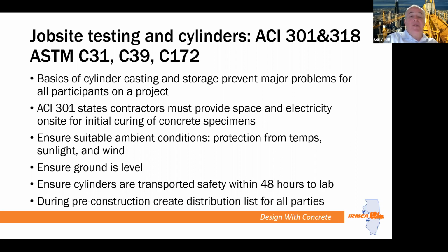And then ACI states that contractors must provide space and electricity for the curing boxes, which is the preferred method of storing cylinders on a job site for initial curing. And it should be a spot that's obviously out of the way of construction activities. And then we want to make sure that suitable ambient conditions exist for protection as well, for temperature, sunlight, and wind.